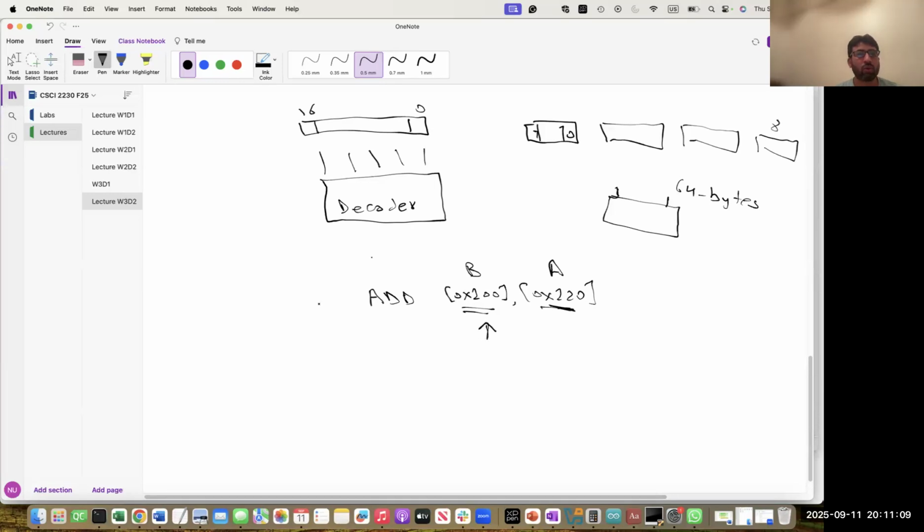So what are you doing? You are completing that same thing in one single instruction. If you compare it with the example given in the slide where we are doing 4 different instructions, right? So the program is faster, but your hardware will become more complex. Why will it become more complex? Because now you need to be able to load the data directly from memory into the ALU.